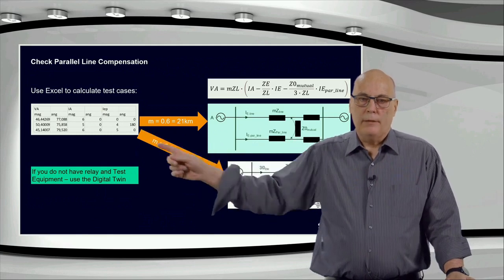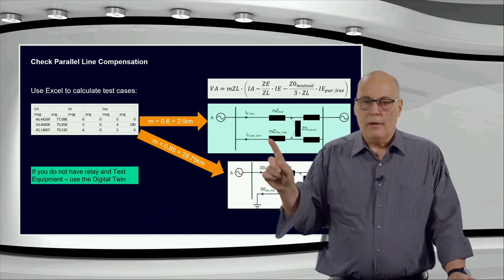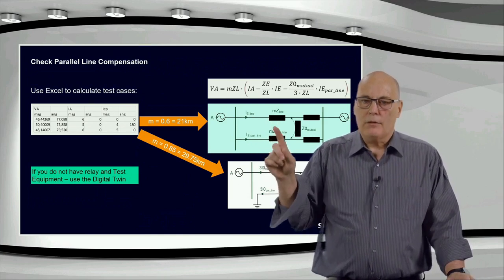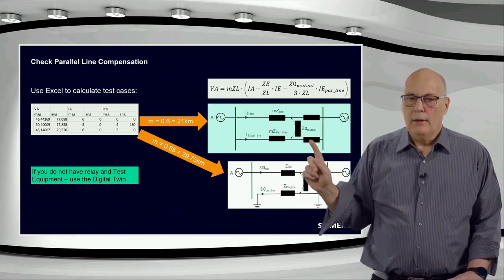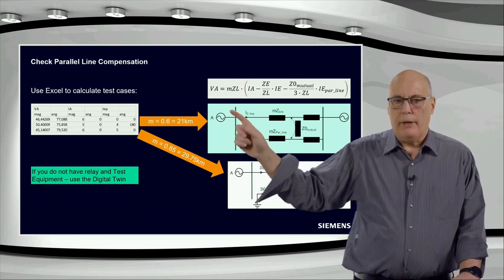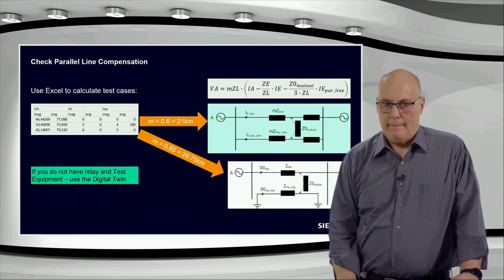So in this second test case we have 5 amps here and 4 amps over here, and the ground currents are parallel. Normal application, remote fault. And again, it was at 0.6, just to compare the two results. So both the first two faults are both at 60%.